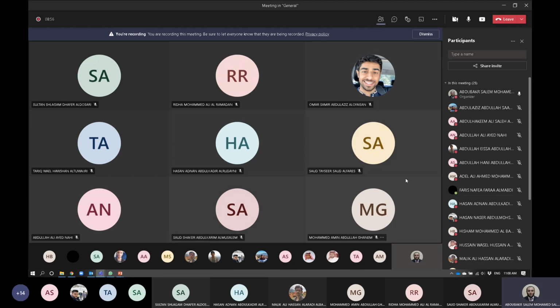We have other types of machines. If you Google it, you will find that we have 5-phase machines, we have 6-phase machines. It's also called multi-phase, and it's used mainly to increase the reliability of electrical machines. If one of the phases fails due to any problem in protection, open circuit for instance, the other phases can work in a different way. This is very important in terms of continuity of loading or reliability.